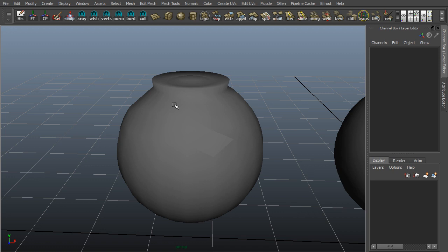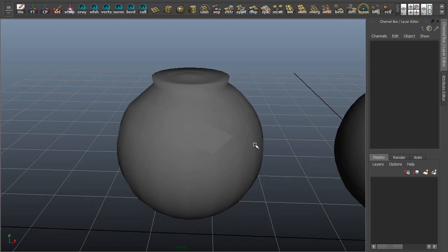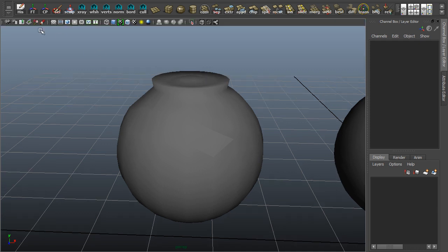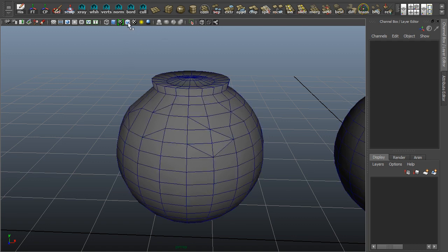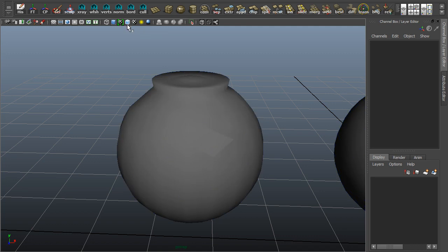So from this point on, this is pretty much how we're going to work. We don't have much of an interface up here. Occasionally, I will hit Shift Control M to get to this right here, but a lot of this stuff I have up here anyway, like X-ray mode, and here is toggle wireframe unshaded right here. We talked about that one. Toggle the grid on and off.